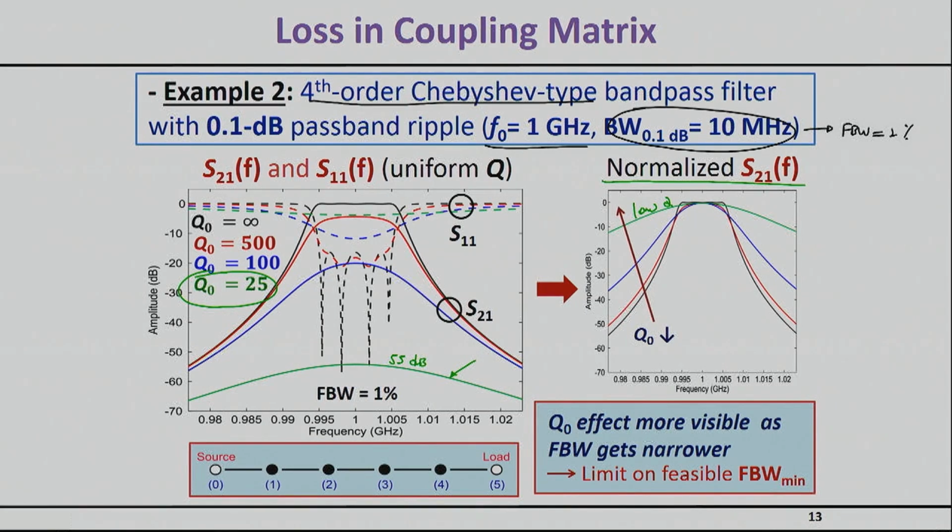So now you might start realizing more precisely why we don't do channel filtering right after the antenna. Let me remind you of some of the things we discussed in the system level discussion. We said that right after the antenna, we will normally select our band. Then we will down convert with our VCO, and finally we will have channel selectivity here. So channel selectivity would not be in the first stage. The first stage would be more band selectivity.